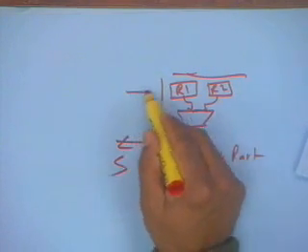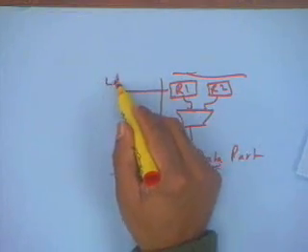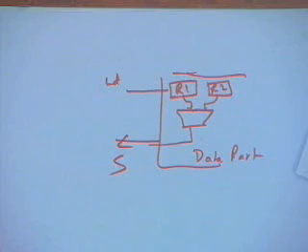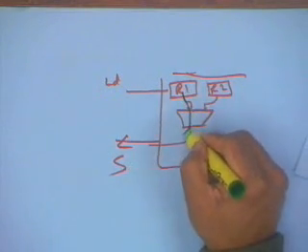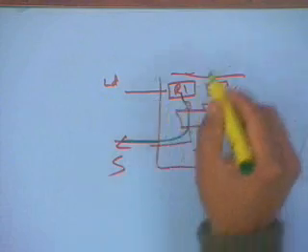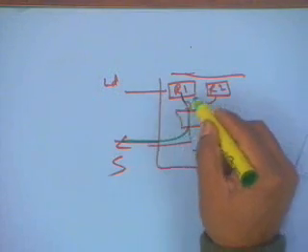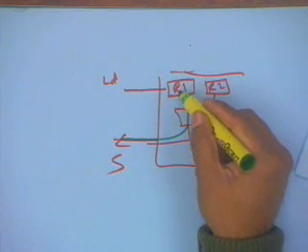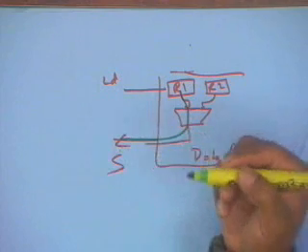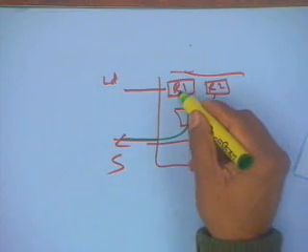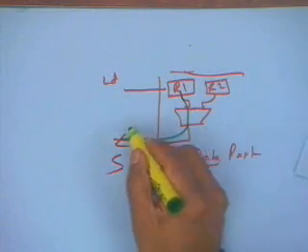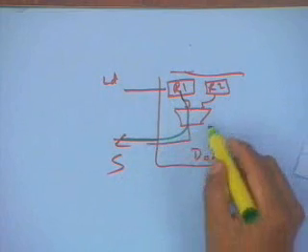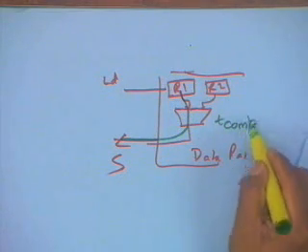Now what happens? Load enable comes from the control for this register. So the delay of this comparator is one T status, because whenever the load signal comes, the register will have some inputs and I will load a value, and after that value comes, the status output will change, because depending upon what the value in R1 is and what the value in R2 is, I may get a greater than or less than output, but I will not get it immediately, I will get it after a delay which corresponds to the comparator delay.